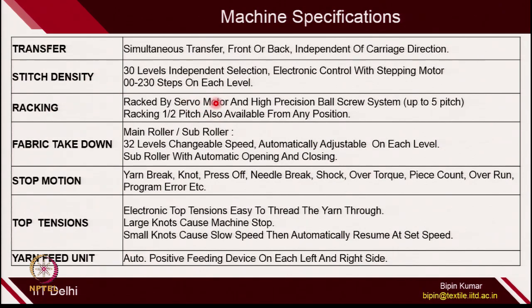Racking, already I have introduced, up to 5 pitch. So, you can shift one bed with respect to the other bed up to 5 pitch. That is really wonderful. Also there is a possibility to rack half pitch, and we will come to the design aspect, and you can see how racking is very important when you are transferring the loop from one column to another column. So, racking is definitely one of the very important functions.